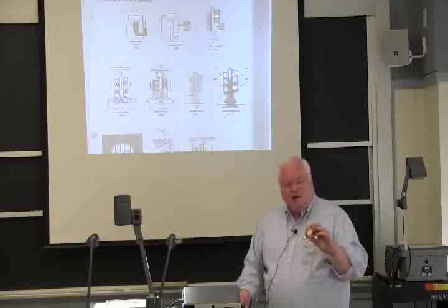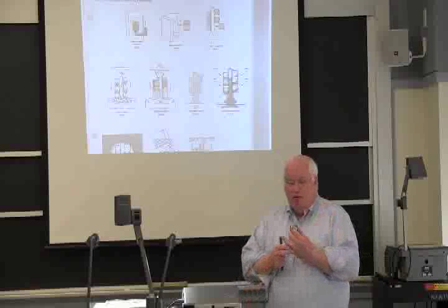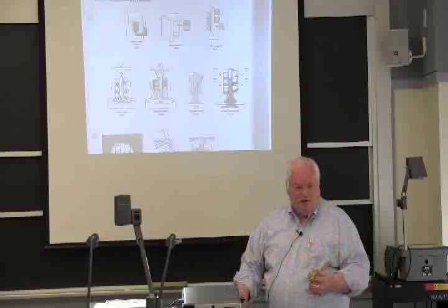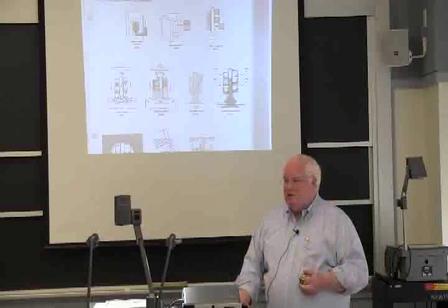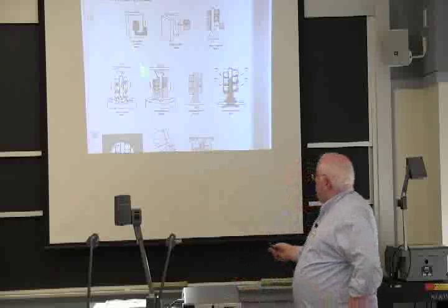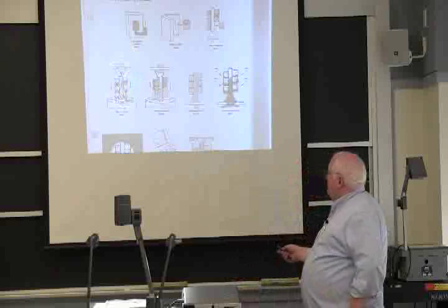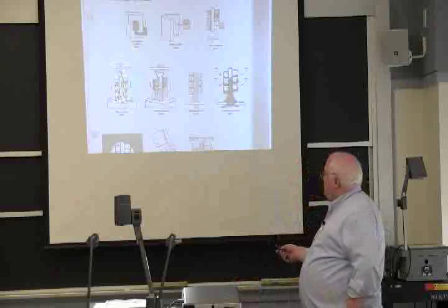This is the big brass rat I think I passed around once. This is lost wax cast. My class ring, any of your class rings, were also lost wax cast, or what we call today investment casting, because you take the plastic or the wax part and invest it in a layer of ceramic.